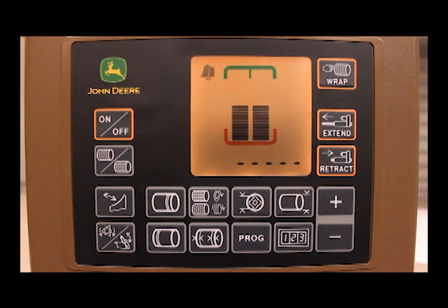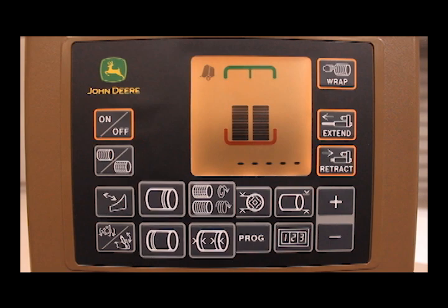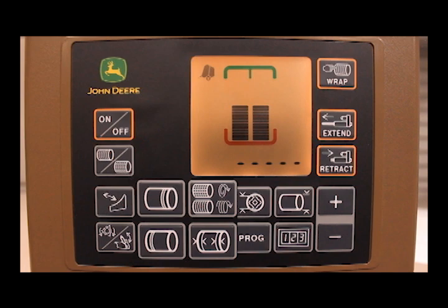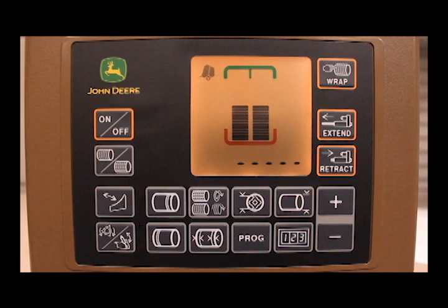The Program key is used to select a preset list of monitor settings for different crop types. The settings that are changed when using this button are left and right hand end wraps, twine spacing, twine end wrap distance, and number of net wraps when using net.